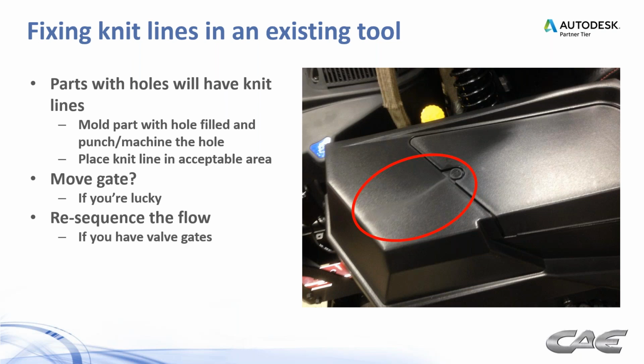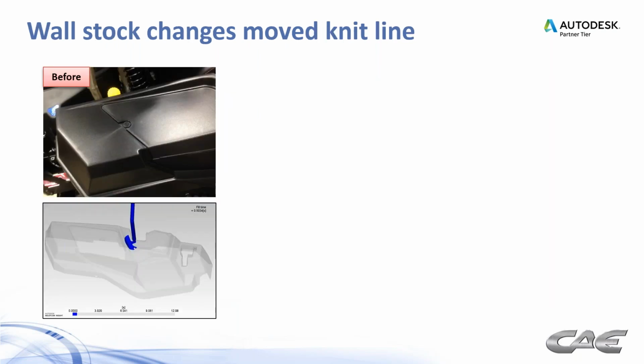If you have valve gates, then that's a possibility, but that's not always going to be the case, of course, again. Or maybe modify the part design, and that is the route we chose in this case here. So we used flow leaders and flow restrictors.